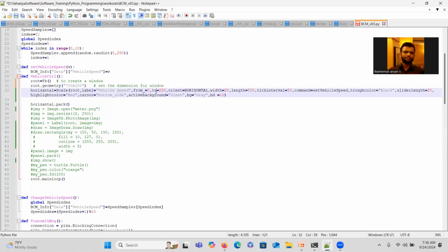Then we have a command. The command is the event procedure. In the case of Panel Designer, we design the panel and attach the system variable. For that system variable or signal, we write a procedure, like on sysvar or on message.